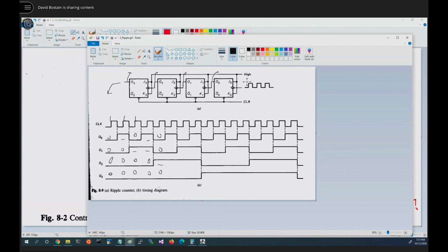Remember we talked last time that this incoming sequence might be coming out of a 555 timer. And it might really be ugly. It might look like this: a long on time and a short off time. So it'd have a real high duty cycle that might be 90%, 95%.